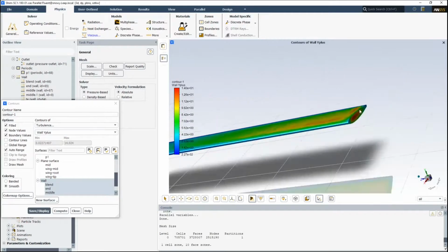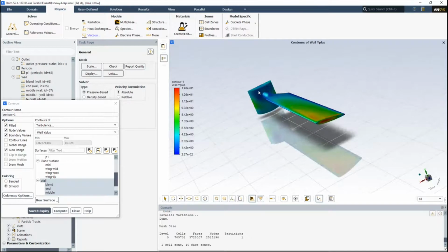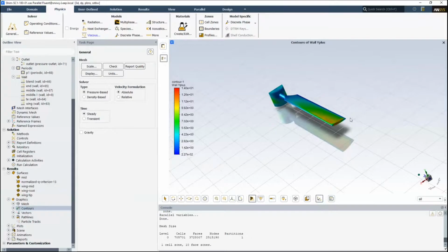So we're doing between a Y plus of 0.02, which is very small, and 14. So it's actually done a fairly good job of picking up the boundary layer for a representative case. Obviously, we want more layers because the more layers, the more accurately we're picking up the gradients in the boundary layer. And upwards of 15 layers is going to be what you're targeting when you want an accurate simulation, but we've done a better job. Okay.